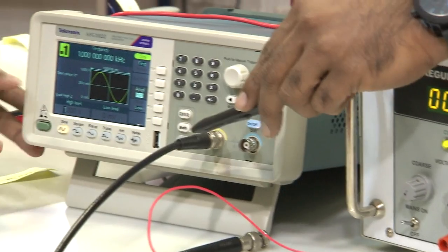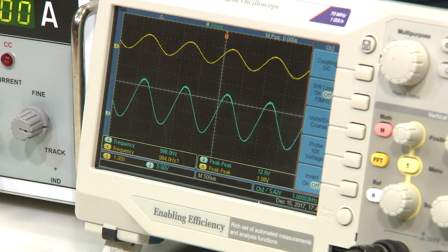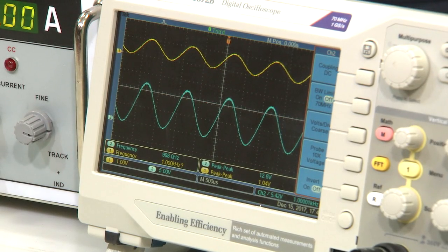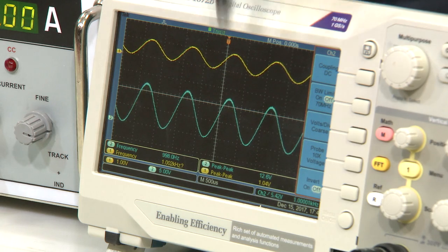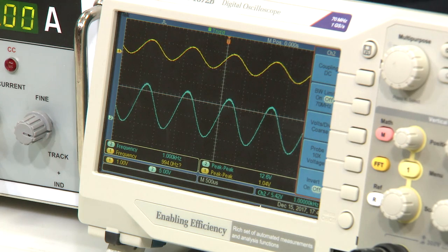So, when you connect your frequency generator, now we are applying a sine wave. We have to now see the oscilloscope: what we see is the amplification of the signal, sine wave of 1 volt, and we get around 12 volts. 1.04 is the input, 12 volts is the output. Phase shift is 0 degree, very easy, right. If you say inverting, phase shift is 180; non-inverting, phase shift is 0 degree. Both are amplifiers, so there will be amplification.